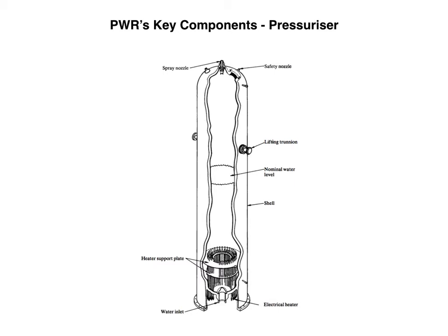Suppose that the power output of the turbine is reduced in response to a drop in the electrical load on the plant. This leads to a temporary increase in the average temperature of the reactor coolant and a corresponding increase in coolant volume. The expansion of the coolant raises the water level in the pressurizer, which raises the pressure of the steam and actuates the valves to the spray nozzle.